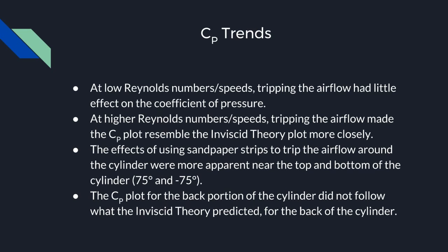So it doesn't matter if it's tripped or not. And then at higher speeds, we can see that the CP follows the inviscid flow theory better once you trip it. And the reason for that is because it turns turbulent and it stays attached longer. And then we can see that